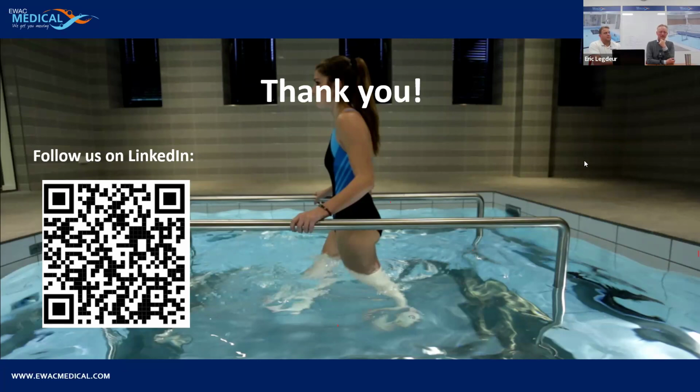The thing is that if the temperature of the air around the hydrotherapy pool would be lower than the temperature of the water itself, you will get an enormously damp atmosphere, and then you will get a lot of condensation on the walls and the ceiling. So we would advise at least a temperature of 3 to 4 degrees higher in the air than the water temperature itself.